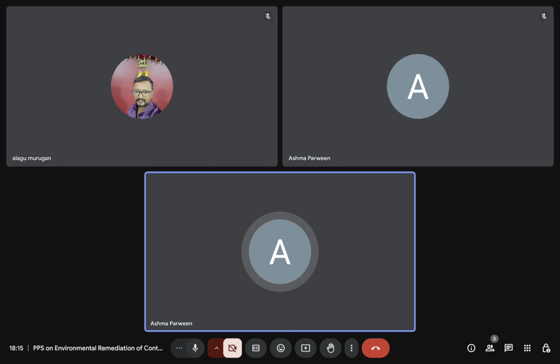Based on this method, since we're dealing with hazardous waste, the solid waste is taken, and the extractant solution is taken in the ratio of 1 to 20, and then they are rotated at around 30 rpm for nearly 18 to 20 hours. After that the concentration of the contaminant is found in the filtered leachate or the filtered supernatant, and in that we find out how much portion of the contaminants is leaching out.